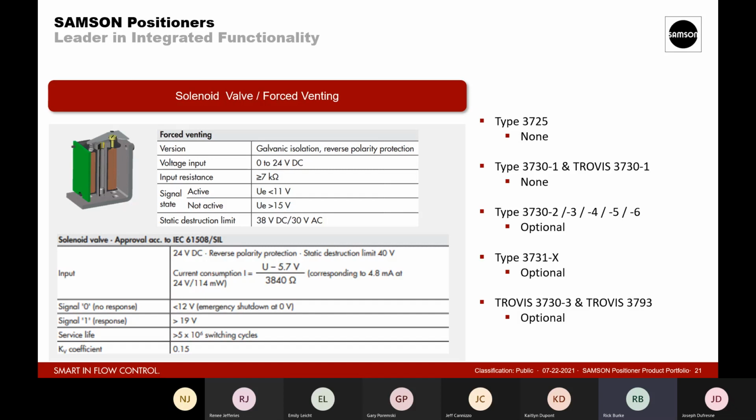I went out to the field and looked at the label, and it didn't have the solenoid valve function marked on there. They hooked up 24 volts to the two terminals for the solenoid valve, but it wasn't doing anything because it wasn't even there. But it's good that the positioner is smart enough to tell them if you know how to look at it.